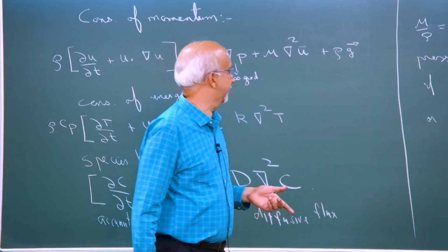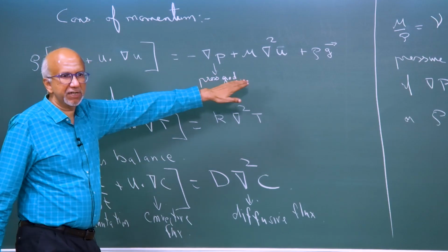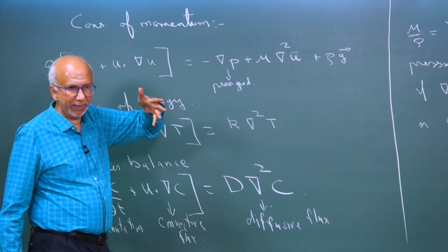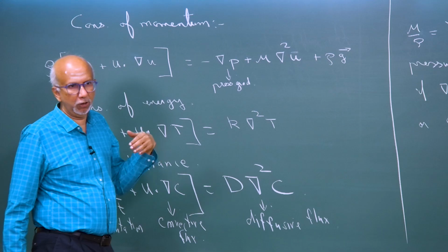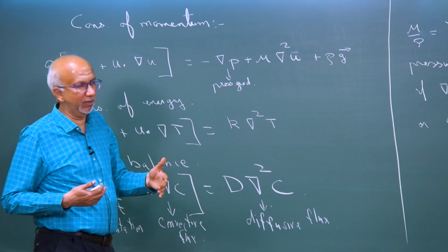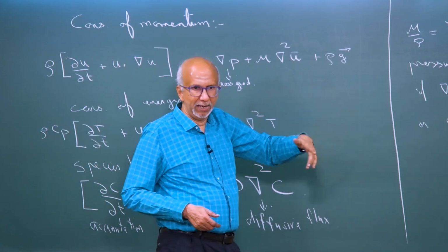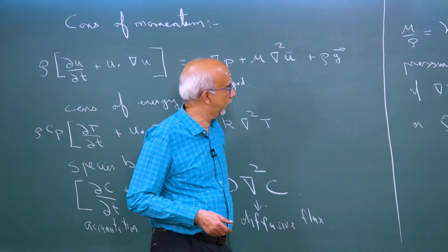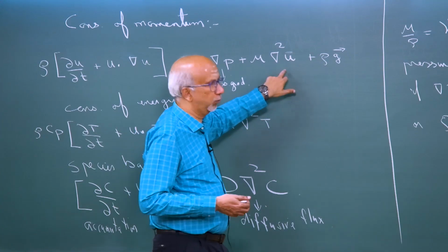So, basically what I am saying is you might see papers or articles where some extra terms may come in depending upon the particular situation. There is a field called electrohydrodynamics, there is a field called magnetohydrodynamics where people put a magnetic field or an electric field, and you will get extra forces here, okay. You have to go back to whatever you learned in your physics, your different laws, like the Lorentz force, for how you calculate the forces, and then you have to include it here, okay.